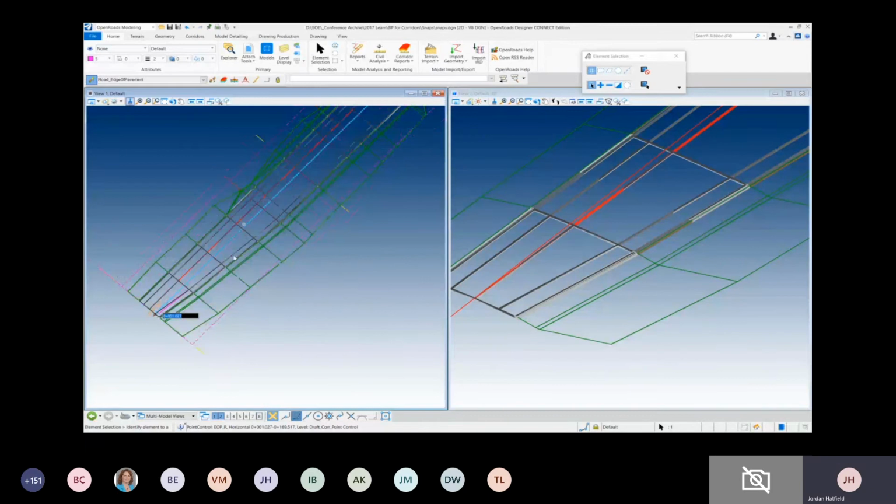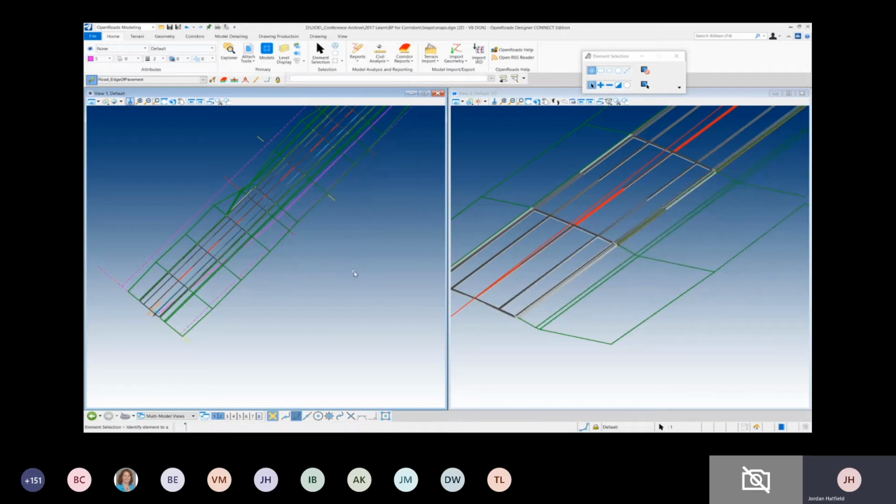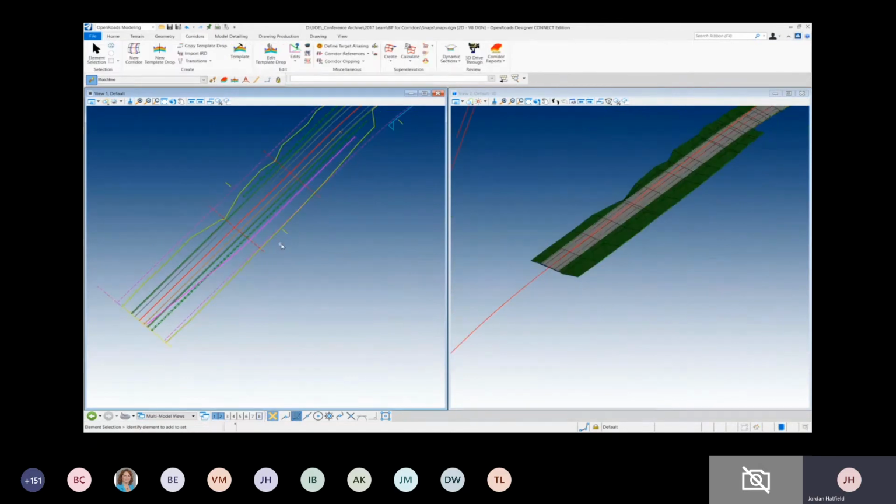start and stop station. I could also get other properties off this. I could go in here. I could just simply delete it, remove it. I could get the information. I could say, oh, that is horizontal. Do I want it to be true or false? How did this corridor look originally? I don't have to go to the corridor object to do this anymore. I can get it right at my fingertips. I can just hit false. And basically at that point, the point control is still stored on the corridor object, but it's disabled at this time. Okay. There's even some more UI improvements.